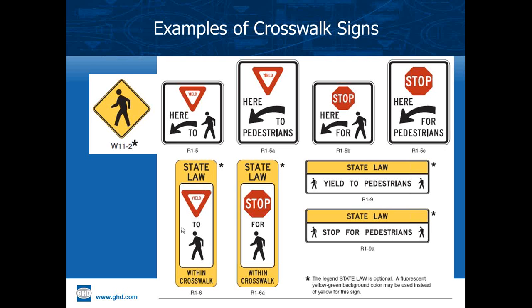Unfortunately, the MUTCD does not prescribe the use of this in the roadway. If it's to be anywhere, I believe it's roadside only. So they're not to be placed on splitter islands, and they're not to be mounted on signs above the ground. So there's a number of restrictions to using it, but I think there are a number of agencies that would like to put in a request to experiment and try to make better use of those signs.